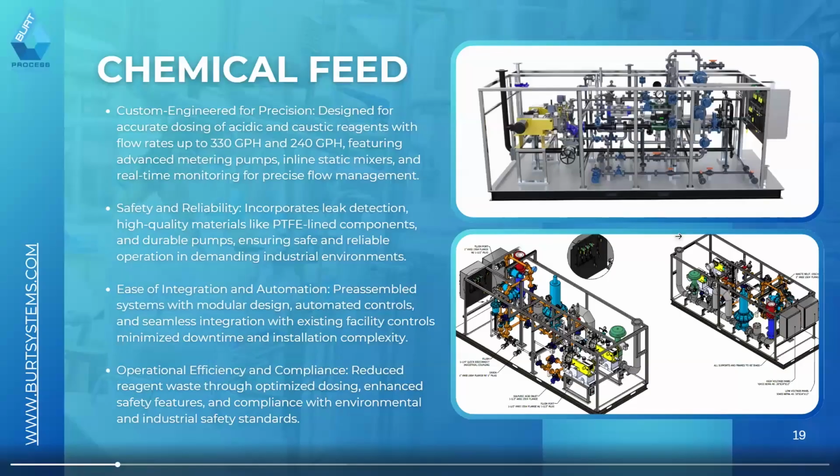Same thing here. This is just another example showing a chemical feed configuration. And not all pH adjustment is actually done on the waste side. A lot of pH adjustment is done for generation, for example, if there's a critical utility plant on site with very large amounts of DI generation, you can use pH adjustment to do resin regen as part of those systems.